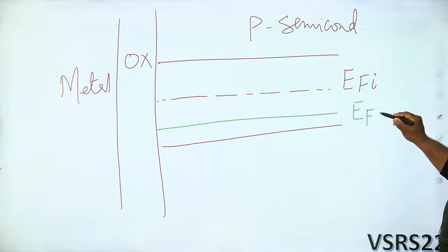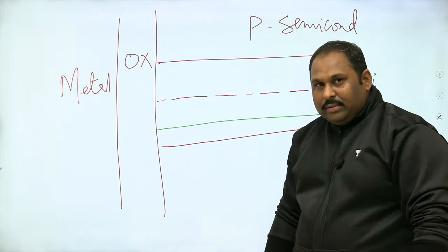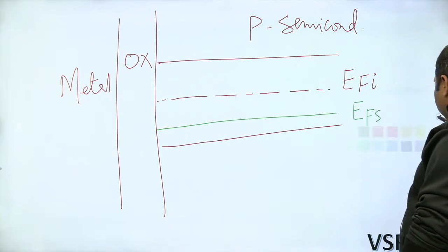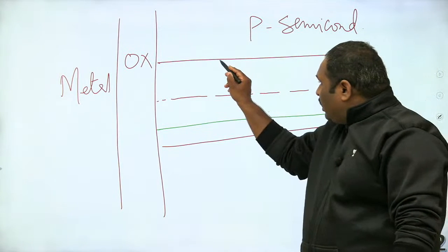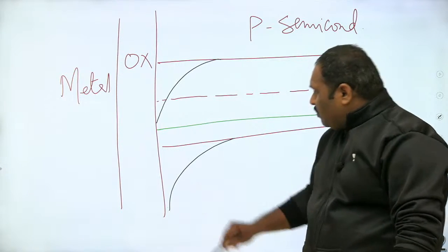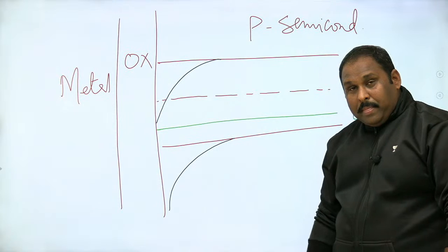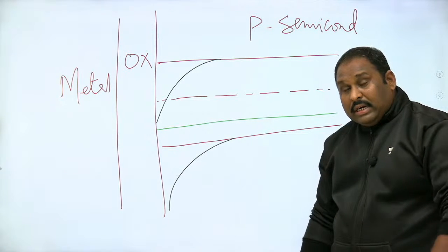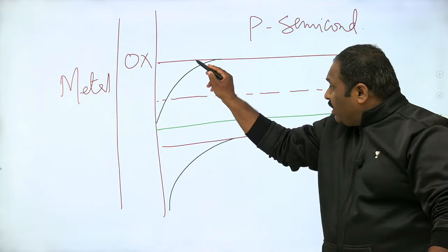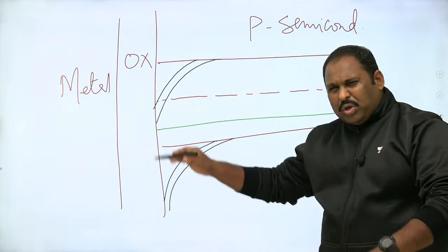This is the Fermi level right now for the semiconductor. If you have inversion taking place, the inversion is such a hopeless situation that the energy levels will drastically drop like this. If the Fermi level gets close to the conduction band... depletion is the state where it may not come very close to it, but still.